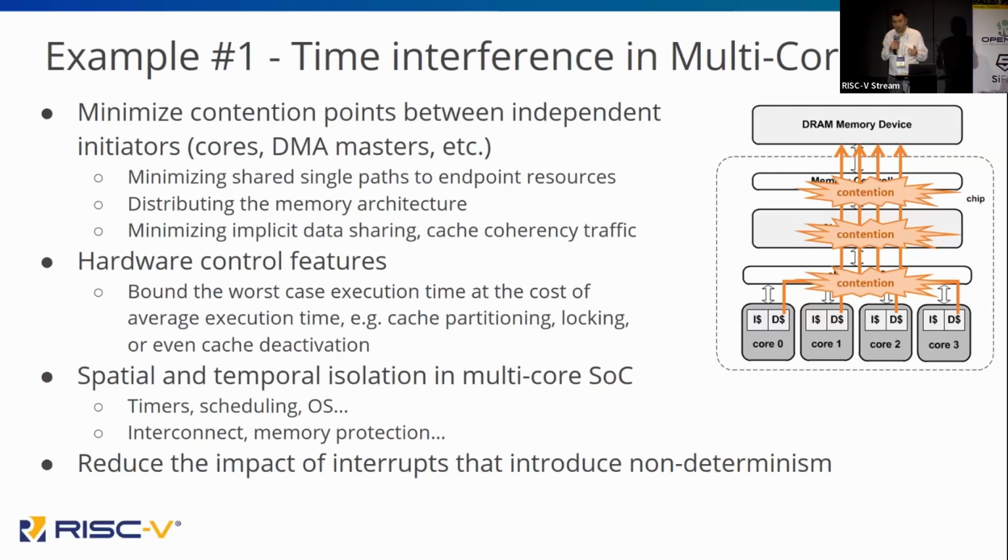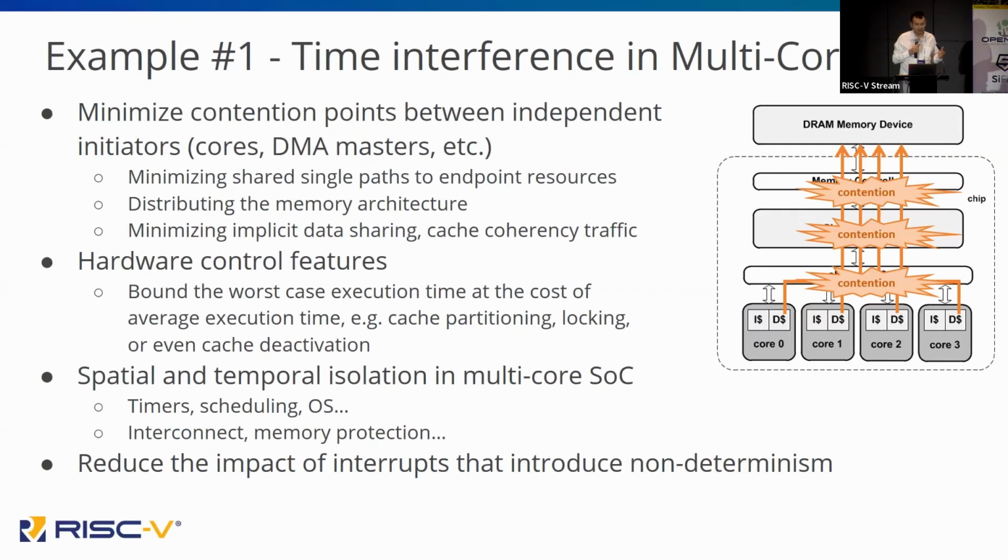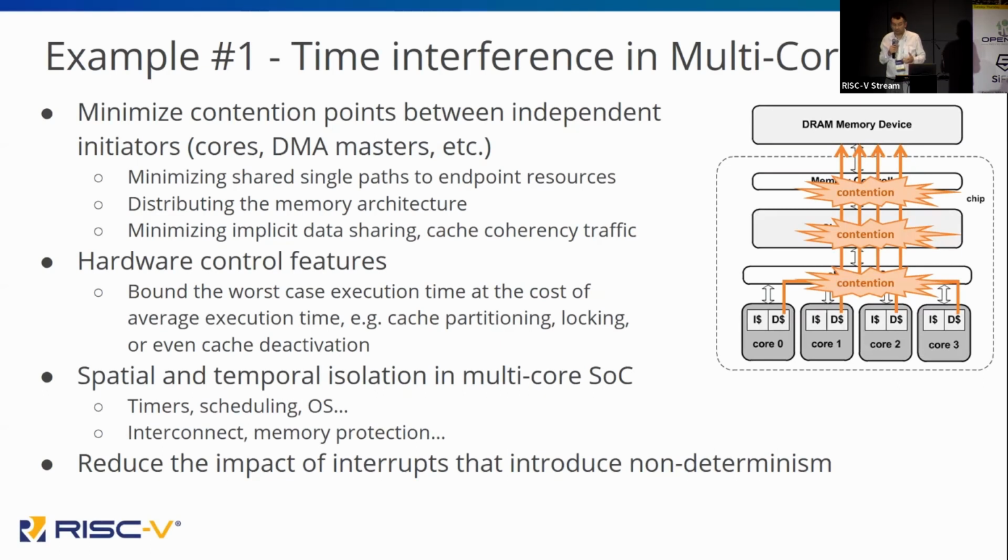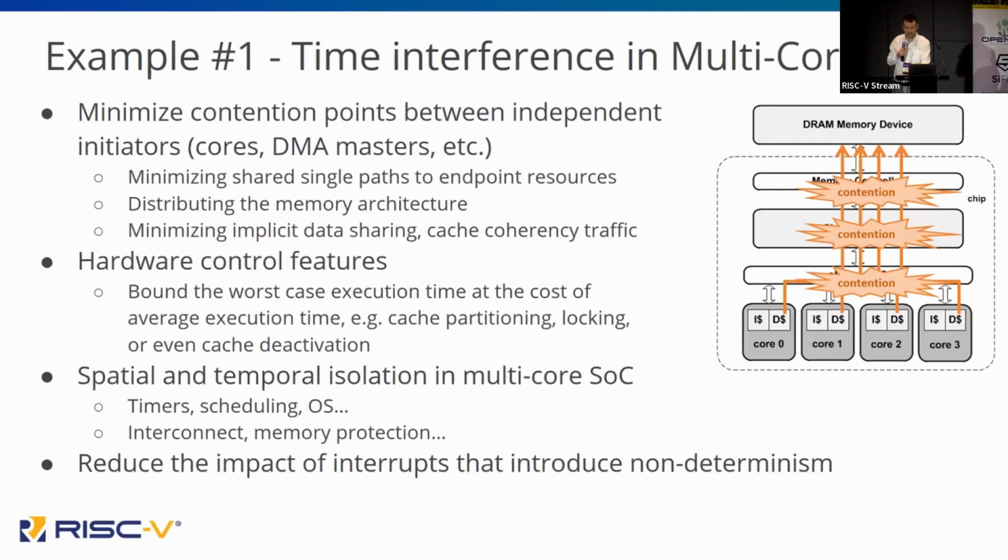At the moment, we are working on spatial and temporal isolation in multi-core SoC, looking at timers, schedulers, OSs, the interconnect, the memory protection. And we can also look at, for instance, the interrupts. When you have an interrupt, this includes non-determinism, and it can be an issue.